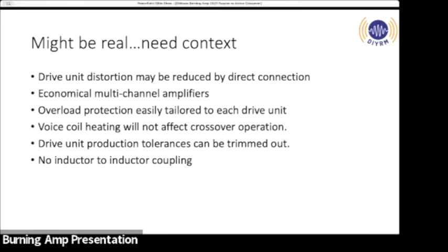The coupling, there's something called precedence effect, right? There's masking and precedence for your ears. And when you look at those curves, you'd be shocked at what can hide. Literally, if you have audible coupling of your inductors, you've zip-tied them together in the worst possible orientation, and even then, I'm not sure. I used to go to the trouble of placing inductors at right angles and at least 6 inches away, but I don't do any of that anymore. I just don't.